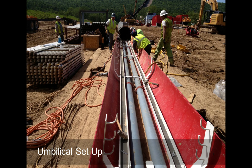So this is a shot of the umbilicals being set up in a half can. The white racks are on wheels, rubber wheels, so they slide in and out of the pipe. The two long gray pipes are the slurry feed and return lines, and then the little white hooks are where the contractor will run power and air supply and guidance and other things from the ground surface to the machine.